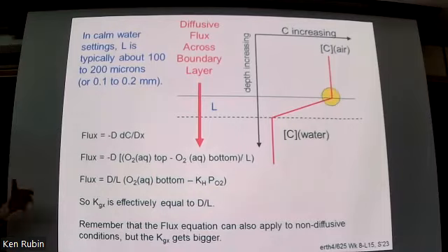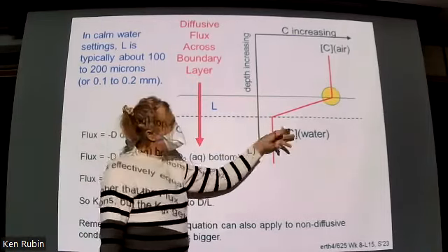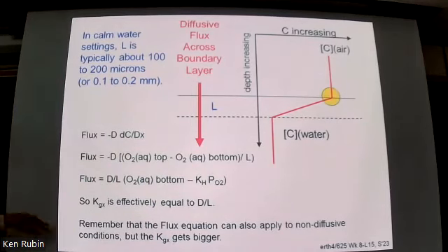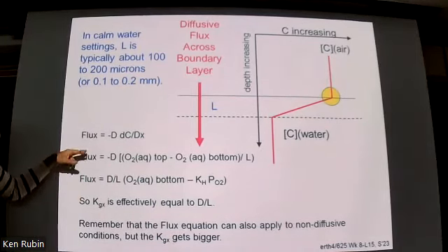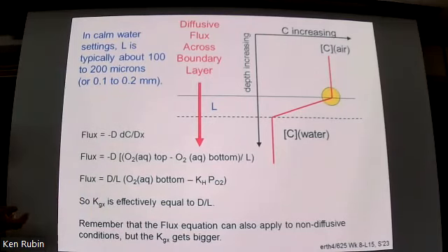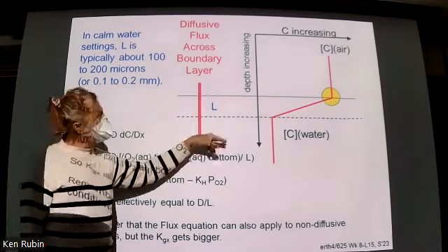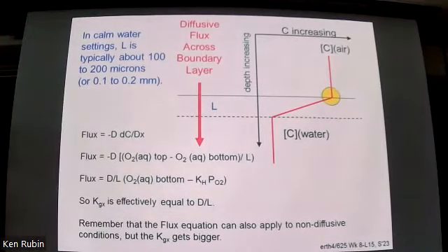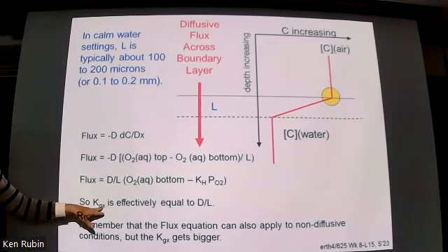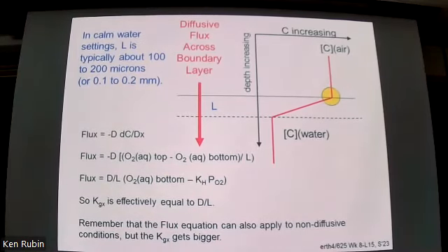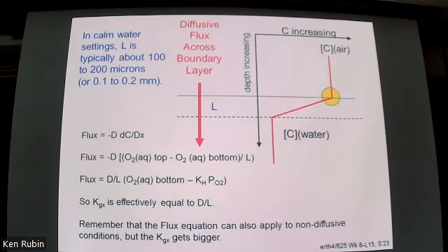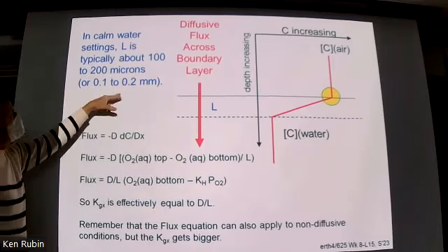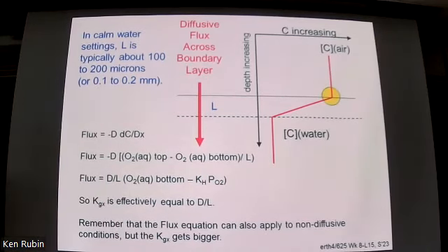So the diffusion we can predict because we know we have high concentration there, low concentration there, and it's trying to smooth that out, so the flux is going to be down, and we can write this out as an expression, the flux expression. I've given the distance x here just as L, a length scale, instead of in units of x, just to make it simple and not confusing with the gx. And you can calculate what that layer thickness is, or you can measure it in various places. It turns out it's pretty thin. It's like 1/10 to 2/10 of a millimeter.